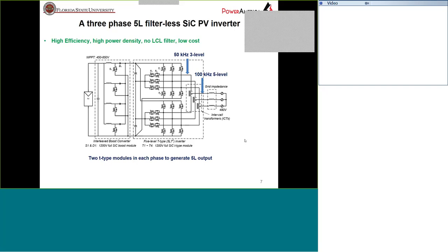Usually in PV inverters, not every customer requires an EMI filter, but we think it's better to have EMI filters because this is a silicon carbide inverter, right? So we are designing EMI filters right now, and our main point of this EMI filter is to make the cutoff frequency of the EMI filter quite high. We are using some notch technology and some canceling technologies to make the resonant point of this EMI filter much higher than the control frequency. So from the control point of view, there is no resonance, there is no filter. But that EMI filter only works for the EMI. Okay, thank you.